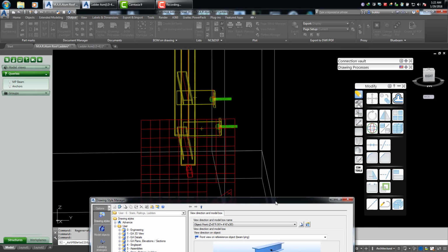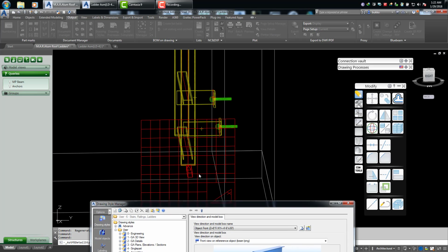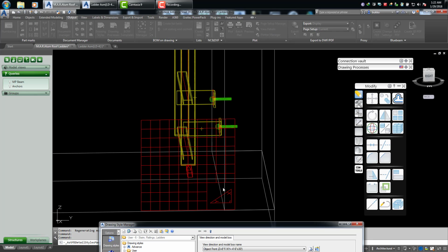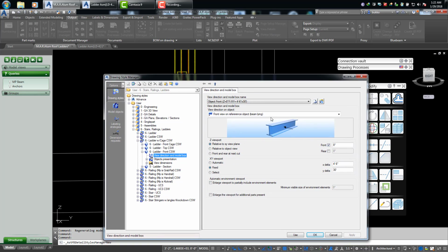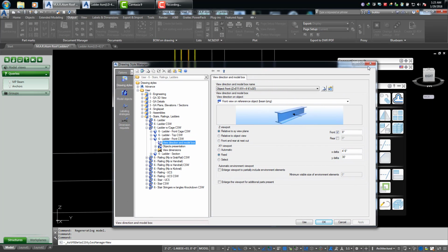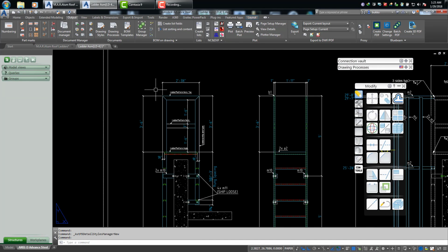When I look at the front view of this part, the main part assembly, it's with this orientation. This is the front view. The XY plane is where you're looking down on it, and this is basically the Z direction. It's kind of hard to get your head around, especially as you start changing these projections, or these view directions. But that is ultimately what you have to learn to understand, and once you grasp that, it makes it a lot easier. So let me go back to the drawing real quick.